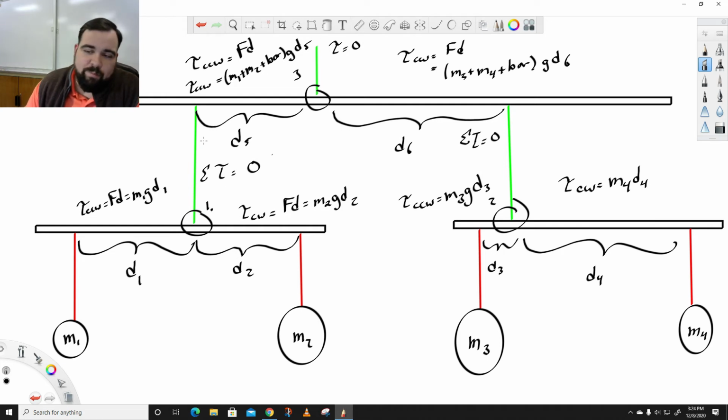Show you balancing the torques on the side over here at pivot point 1. Show you balancing your torques on pivot point 2. And then show the calculations for 3. Once you've shown that you've theoretically solved for all of this, try putting it together. Go ahead and tie it all up, get it balanced, and take a picture showing your final result.